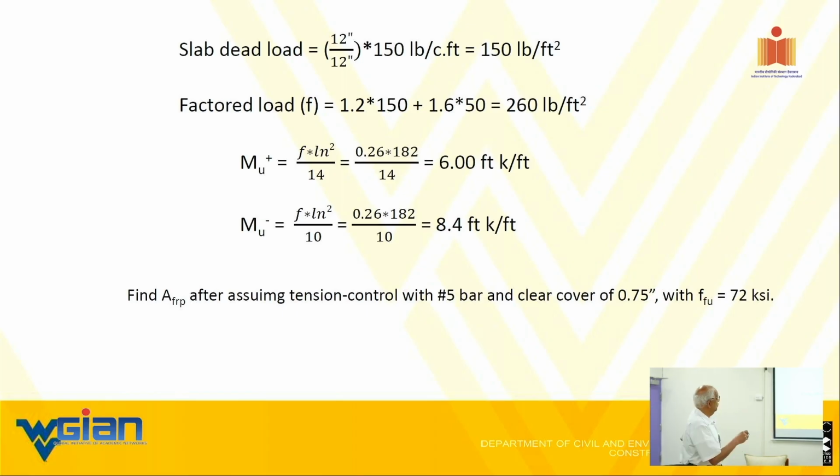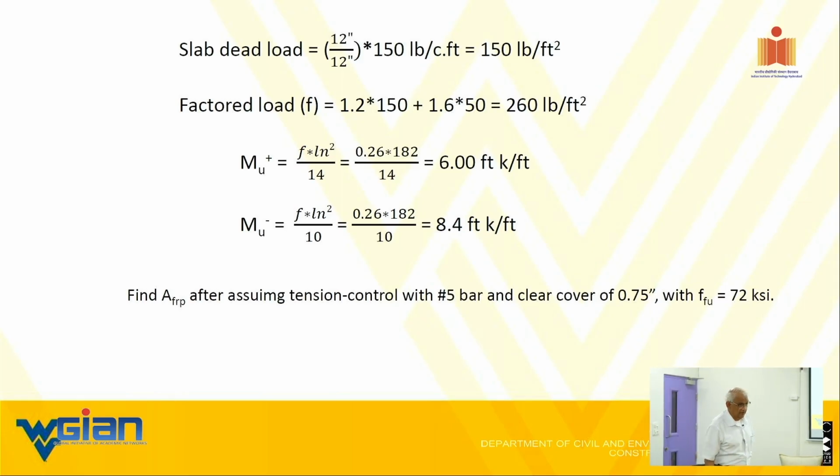This is only one check on that table we just showed you. There are 6 other checks to make only in the strength aspect. Likewise, you have 3 other checks in the serviceability aspect. There are a couple of other checks for extreme events and for fracture and fatigue. So this is an involved process. If you don't have a fracture or fatigue issue, you don't have to check for it. But you must check for both strength and serviceability.